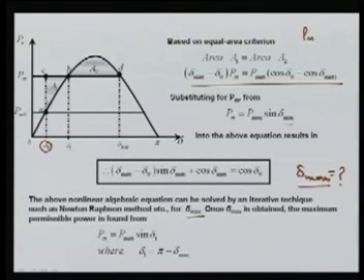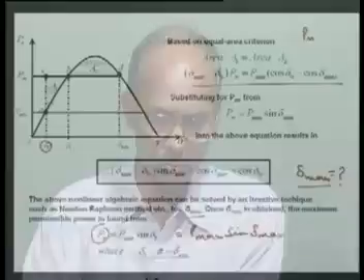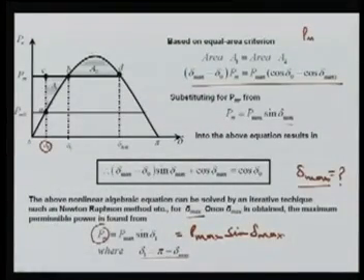Here delta 1 is pi minus delta max, or you can simply write this P max sin delta max. So this will be the maximum power that you can load above this PM naught without losing stability. So this is one way to determine how much you can load suddenly. The question here is, if you are continuously increasing, then your maximum loading is up to P max.